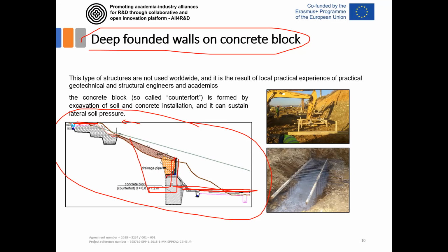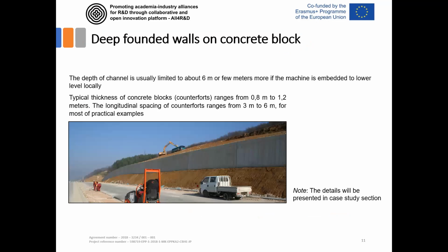But if you prepare a relatively lower height wall supported by the counterforts, then you can combine. Here is how the counterfort looks. Here is the excavation process of the counterfort. The counterforts are locally built at a spacing of 5 or 6 meters or something else, depending on the soil condition and the calculation results. And here you apply this footing. So this is first excavated here, and then the counterfort was constructed. Then the wall was constructed, and it was backfilled with this material. Only after that, this excavation was performed here.